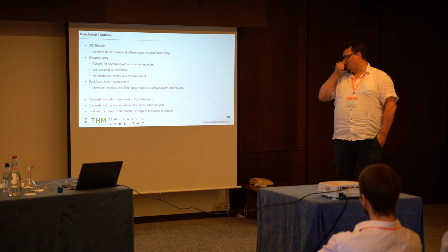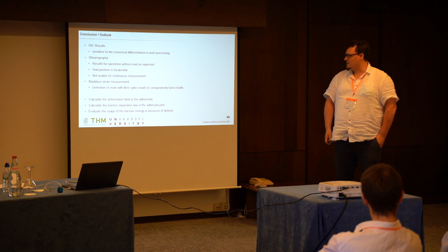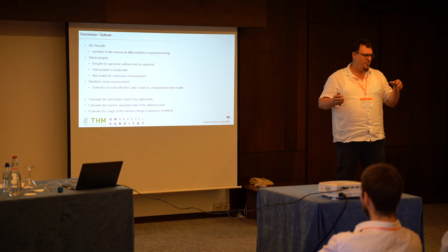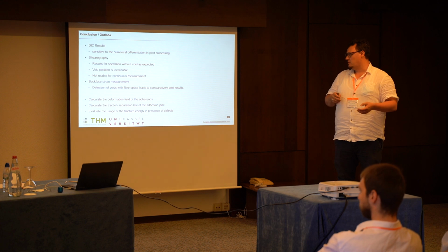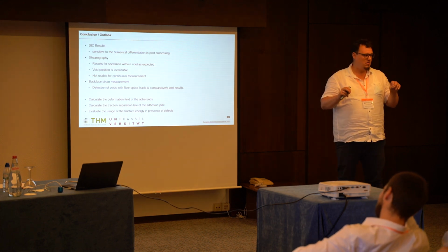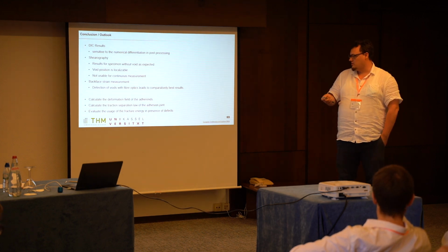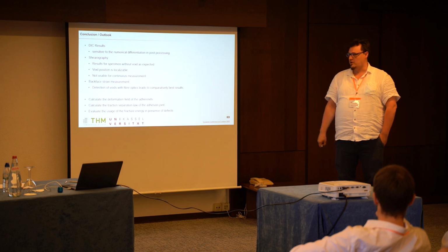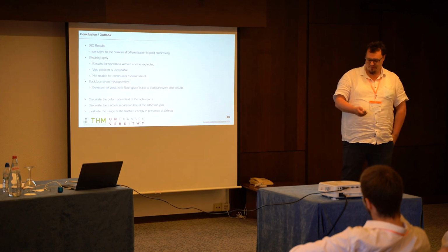Now some words to the future work. With these measurement methods, we want to calculate the deformation field of the adherent, and with the backphase strain measurement, I think we're able to calculate the strain in the adhesive layer for this one-dimensional problem, and we can evaluate the energy release rate, and I hope we answer the question how we can use the fracture energy in presence of defects.